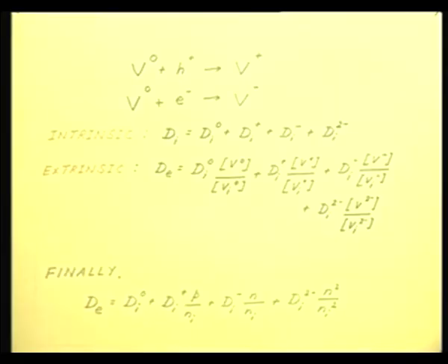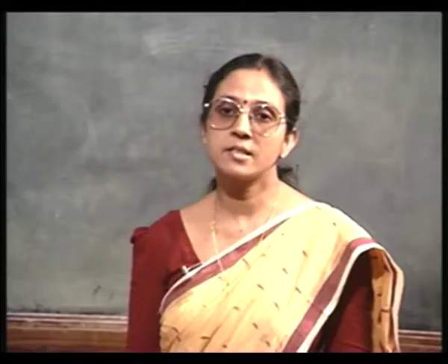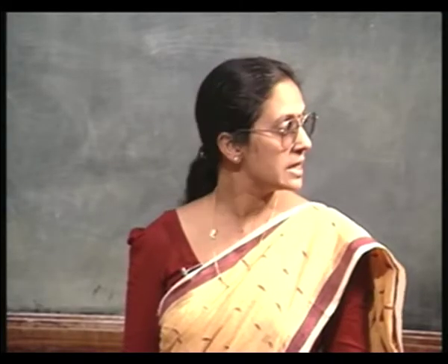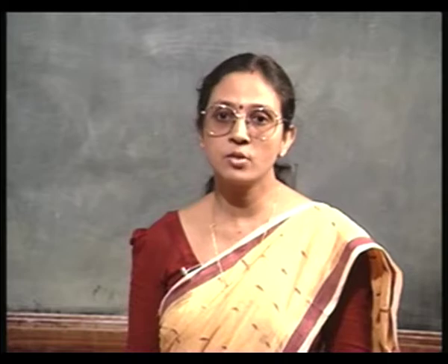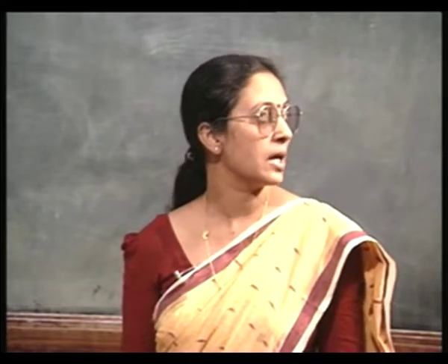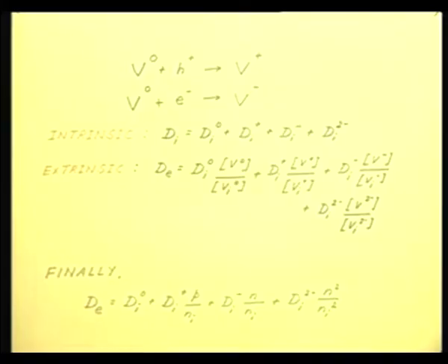So, you see, in the extrinsic case also I can analogously define the extrinsic diffusion coefficient dE as dE0 plus dE plus, dE minus, plus dE double minus.